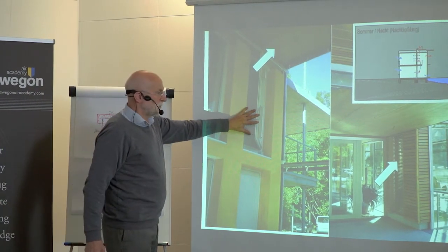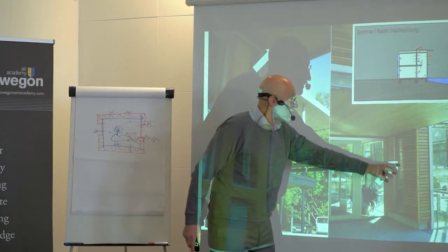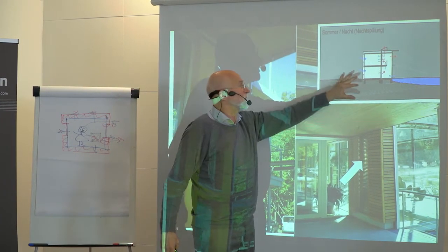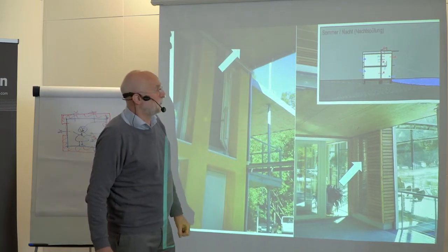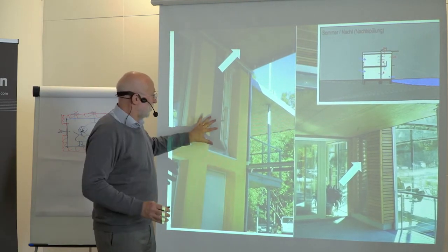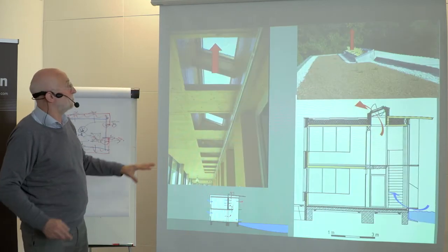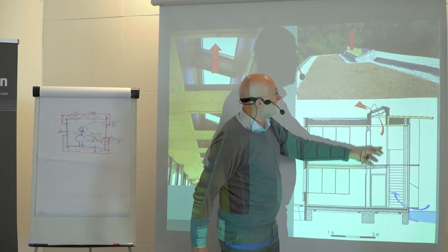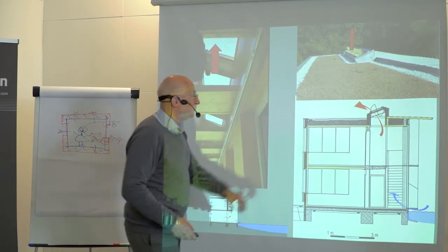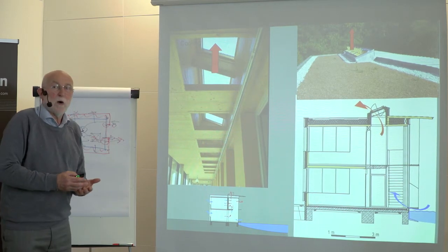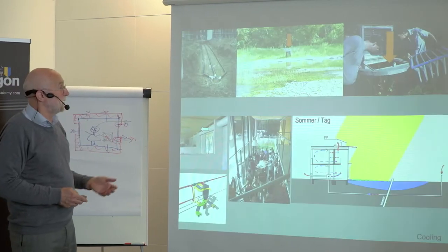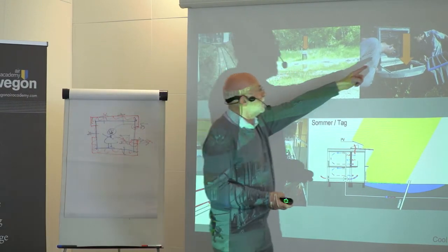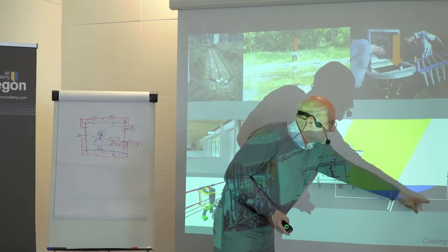Night ventilation, automated, sealed against robbery. It's in the Vienna Woods, and it gets cold during the night, and the building mass is also brought down to night temperature by good ventilation. It ventilates through from the deepest point to the highest point, so that the building mass is cooled down. It's the second strategy. There's a third strategy, that the fresh air comes in here, goes under the lake and